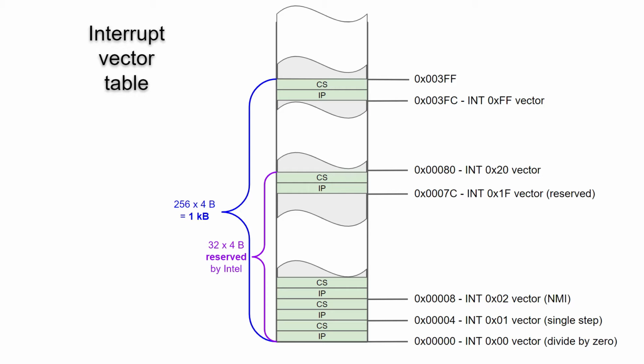We will attempt to raise all types of interrupts and see the CPU's response in a minute, but first we need to learn how the CPU knows which of the 256 vectors to use at a time. Some of the interrupts are simply assigned each to a particular vector. Intel reserved the first 32 vectors from index 0 to 1F in hex to be processor generated.